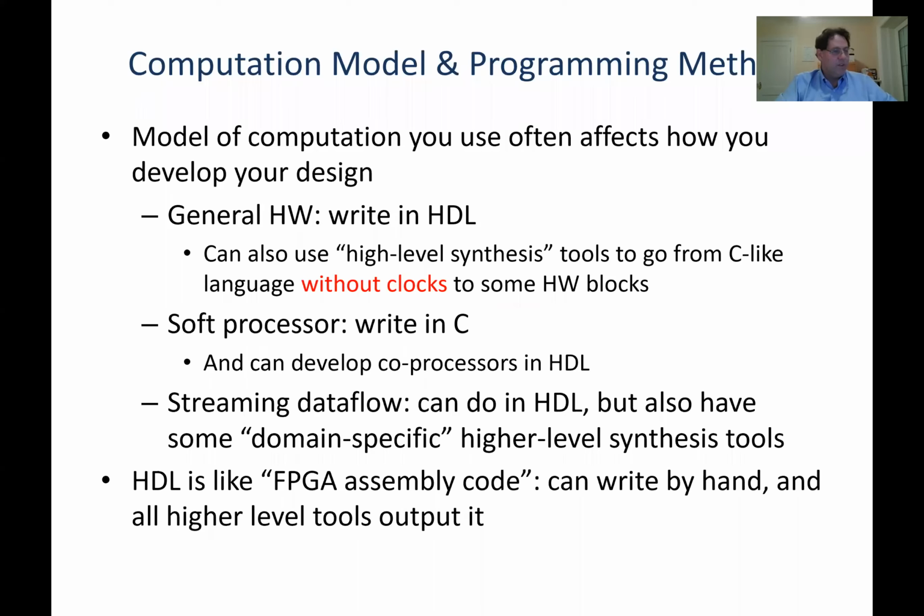We use synthesis to map the HDL into the chip, but it does describe the cycle-by-cycle behavior of exactly how you broke down the computation. And high-level synthesis doesn't. It describes the computation, but it doesn't tell you where the clocks are. So that's the additional step. Out of that comes Verilog or VHDL that can go through the rest of the CAD flow.